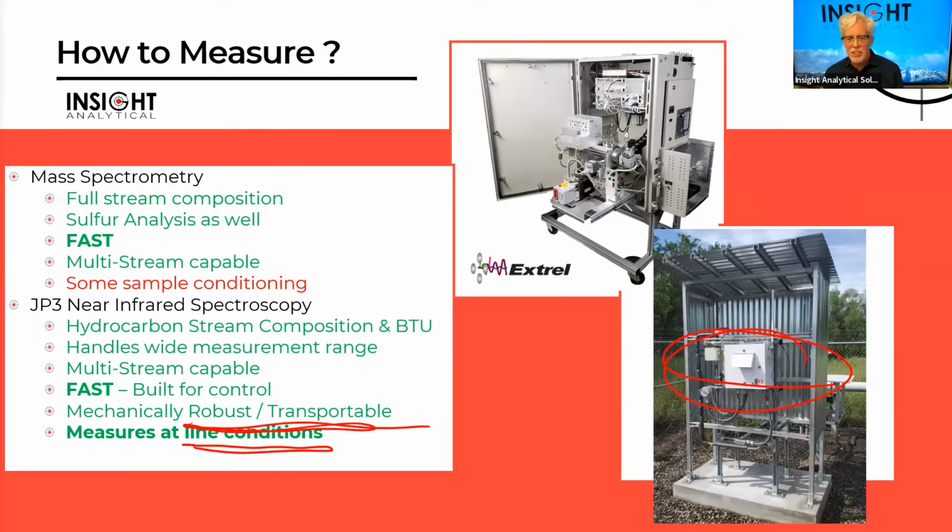So if we're going to put this on something like a mobile compression skid for fracking wells, oftentimes when these guys go out to frack a well, there are not great highways out there. You go down back roads, so you want a device that's going to be mechanically robust and can be moved. And when you get it to site, it has to start up fast and be up and running. Some of the important things we're able to achieve with this technology are to handle that widely variable stream composition, to measure at line pressures and temperatures, not introduce any phase changes, and get that measurement up and running immediately when it gets on site.